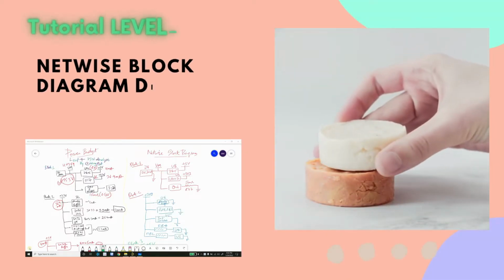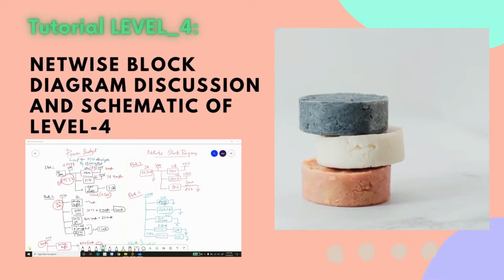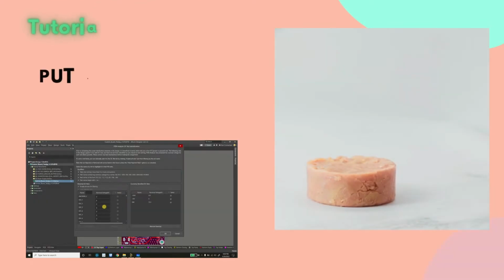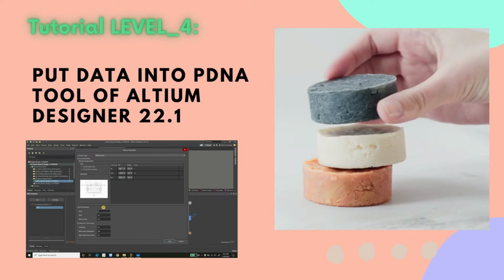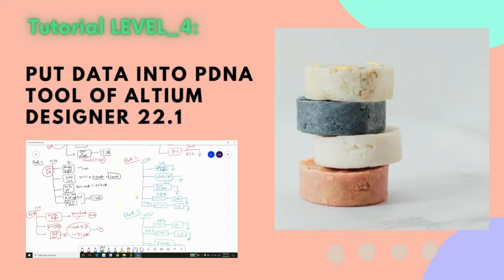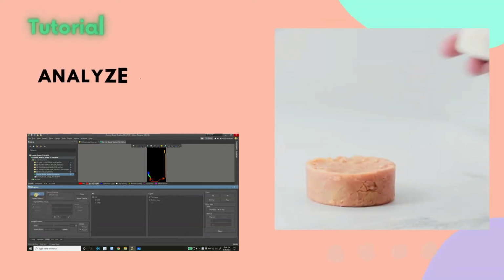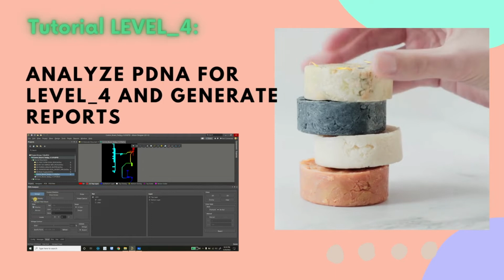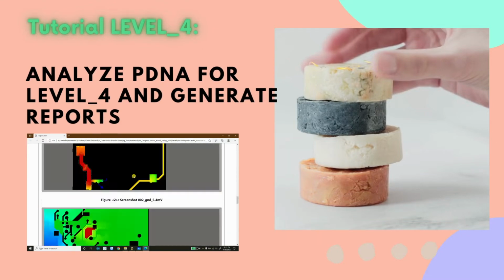We'll start with a little bit of discussion on the netwise block diagram and how I've created it using schematic design. Then we'll put all the information from the power budget and netwise block diagram into the PDN tool of Altium Designer, and then we'll simulate it. After simulation, we'll analyze the results and try to implement fixes in case of any fails on our original design. Then we'll try to make the simulation work for all the test cases.